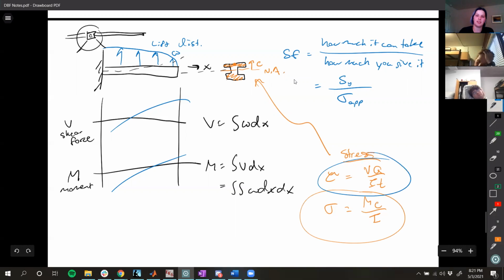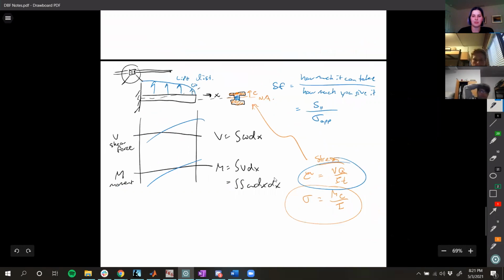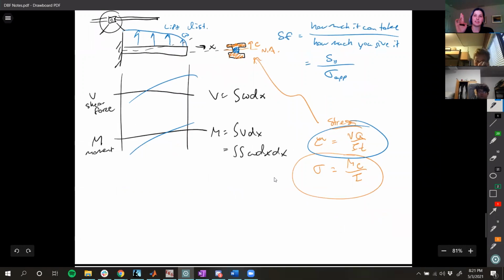And then your shear is held mostly by the shear web. So there are those two stress states, and so you need two different kinds of elements to handle that well and efficiently.